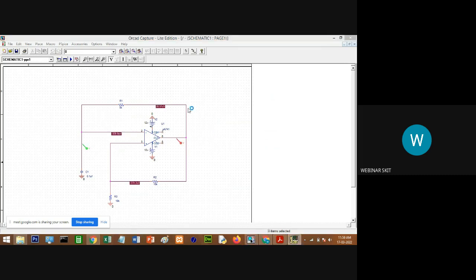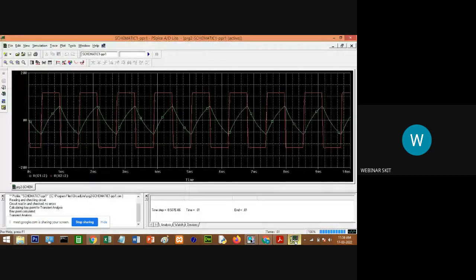Once you click on run, the color of your circuit will change, and here in the taskbar you can find that output window. Just click. See, this is the exact output. This is the square waveform, because of the voltage level marker that we have connected at pin number 6. And this is the sawtooth waveform, that is the capacitor waveform. See, this is capacitor charging and again discharging, charging, discharging. This is the capacitor waveform we are getting, because we have connected the marker to pin number 2.